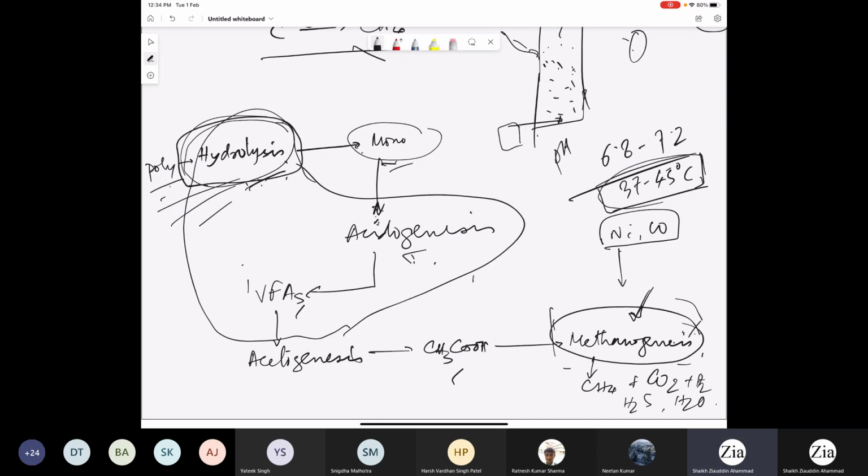That is quite significant, and still the amount of methane generated at industrial scale is sufficient to raise the temperature of the reactor. If you maintain the reactor at 37 to 45 degrees centigrade, you will also enhance the production of biogas. Suppose you are producing X liters of methane: you spend 40% for heating the reactor, and 60% you can still use for electricity generation.